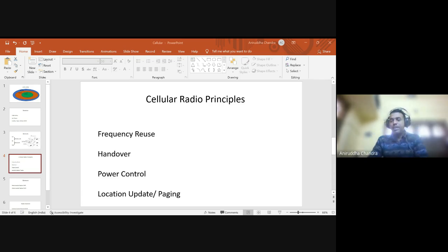Well, with this power control, the tower also knows whether there is a possibility of handover or not. Suppose you are continuously going away from the tower, that means your power levels are continuously decreasing. So when the tower sees that this person is continuously moving away, it is very likely that this person will soon be out of my coverage area, so I should probably notify the network. So the tower sends a signal to the mobile switching center, and the mobile switching center identifies all the nearby towers and asks them to start monitoring this person. So they also start power control.